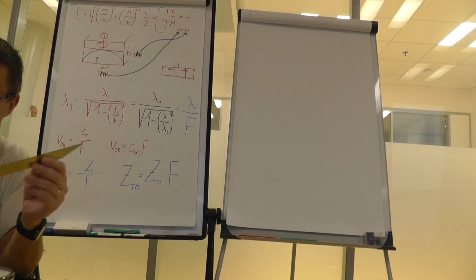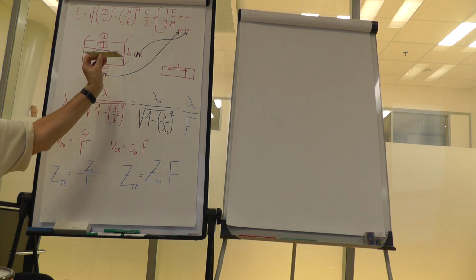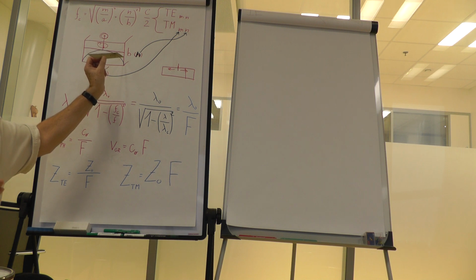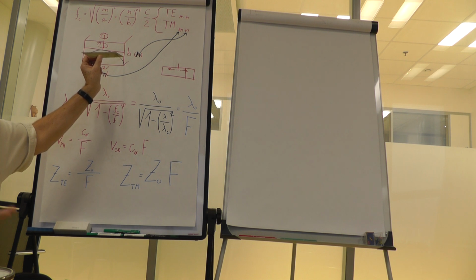In this case, again, if we put the dielectric to the wall, it will not interact with the propagating wave because the electric field within the dielectric will be zero anyway. And the dielectric is non-magnetic or paramagnetic, so that it does not care for magnetic field.